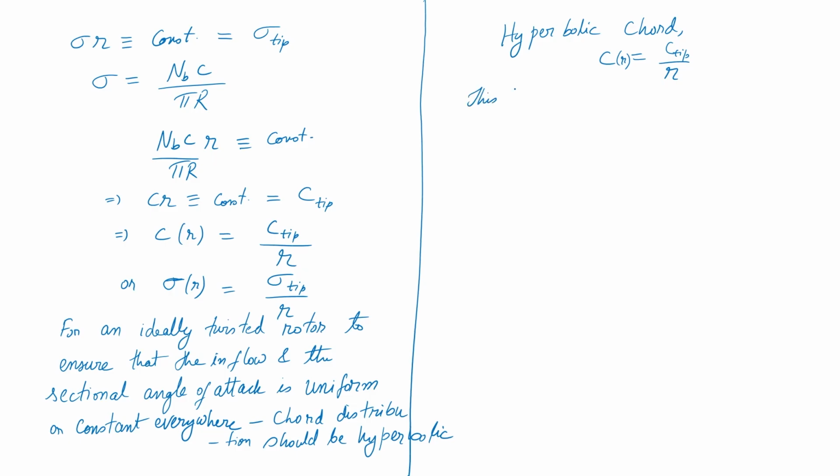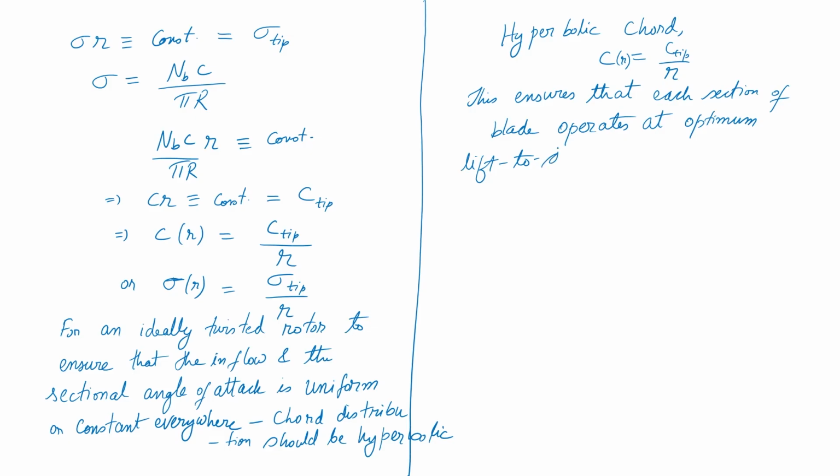So, this ensures that each section of blade operates at optimum lift to drag ratio. Okay, so, hyperbolic chord ensures this.